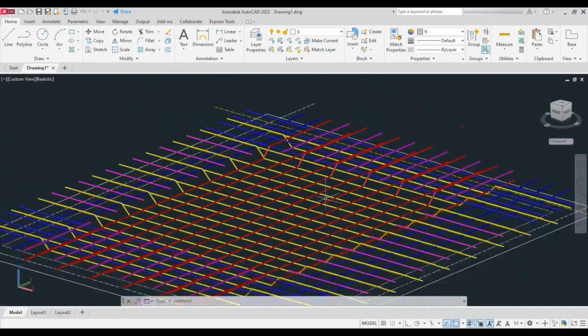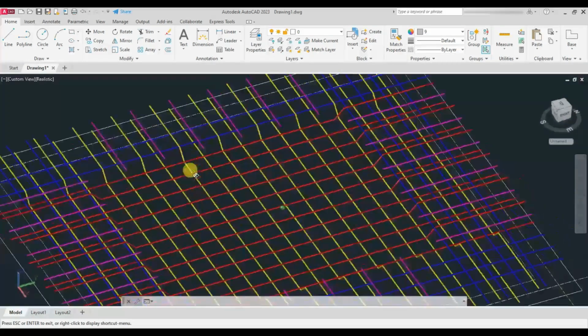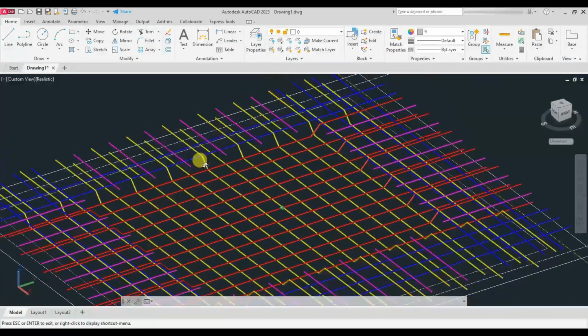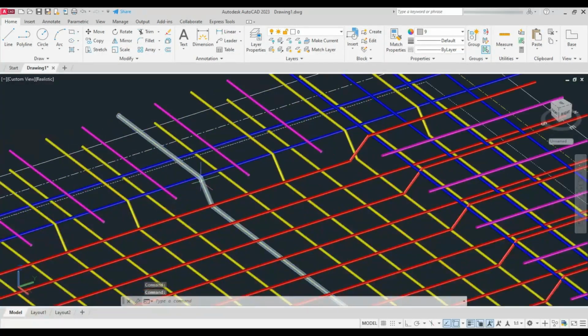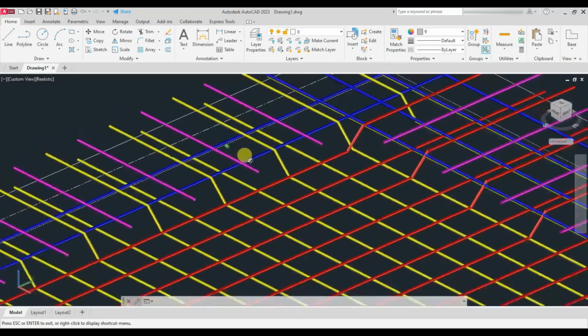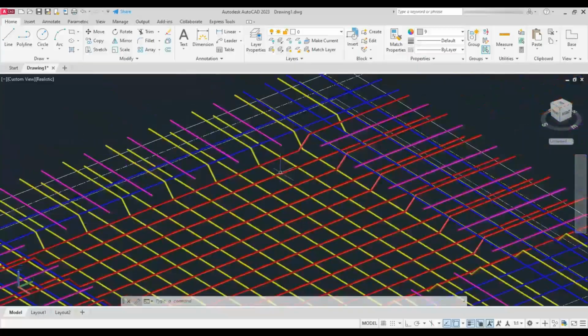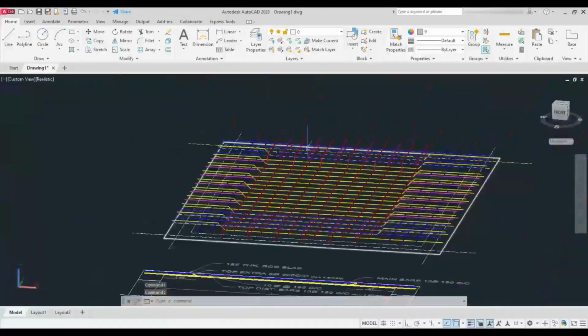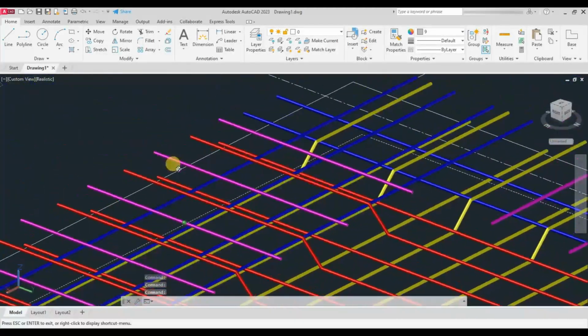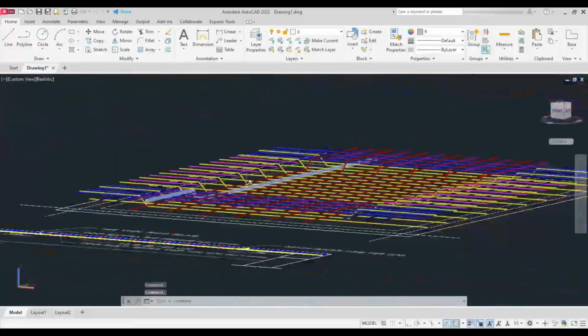300 mm. As the main bars are alternative bent up bars, from bottom it is 150 cc, but at top it is 300 cc. So that is why the top extras are provided, so that the center to center distance is maintained at 150 mm. These are represented in pink.